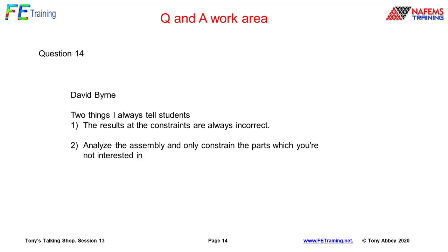It's basically whenever we take a component like this out, like the Conrod we're showing here, and we constrain it, by definition, those are incorrect. It's going to be a more subtle load path through, and it is going to be a distributed reaction, not a constraint to ground. So I think what you're saying there, David, is that let's put the next component in, model that, probably contacts between those, and then somewhere to ground, like the I-beam and the cross members. There I put the cross members in and constrain the end of the cross members, which I think is exactly what you're saying there.